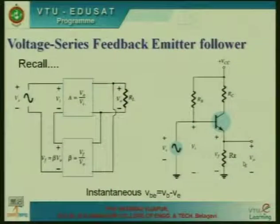Obviously, the voltage gain will be less than one; the maximum possible is 1. So, the output waveform resembles the input waveform. So, it is also called an emitter follower circuitry. The base to emitter junction is forward biased by a resistance RB, and the collector to base junction is reverse biased by the supply and the RC.